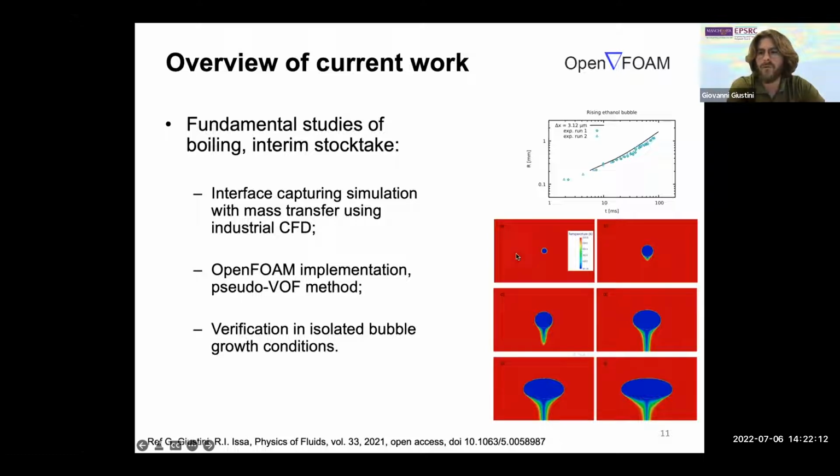Here I would like to show some results of the application of an interface capturing simulation technique applicable to mass transfer that we have implemented using the open source library OpenFOAM. These are verification cases in experimental conditions taken from the literature for the case of isolated bubble growth.